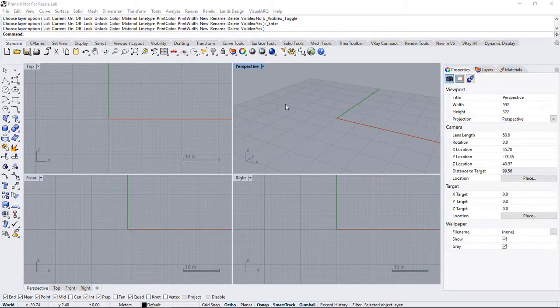There are toolbars collapsed within certain icons. If you click and hold any of the icons with a triangle at the bottom right, you can access the related toolbar and drag it to make it float on top of the interface. Drag it by the purple title bar and dock it to the side of the standard toolbar.